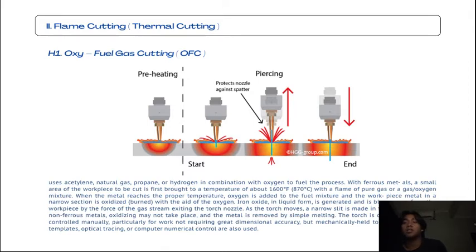When cutting stainless steel, metal powders or chemical additives are incorporated into the stream to improve the cutting action. Some machines have multiple torches and can cut a number of parts from one piece of sheet or plate material at the same time. The part most commonly cut is flat plate, and material from 1/8 to 60 inch in thickness can be cut.